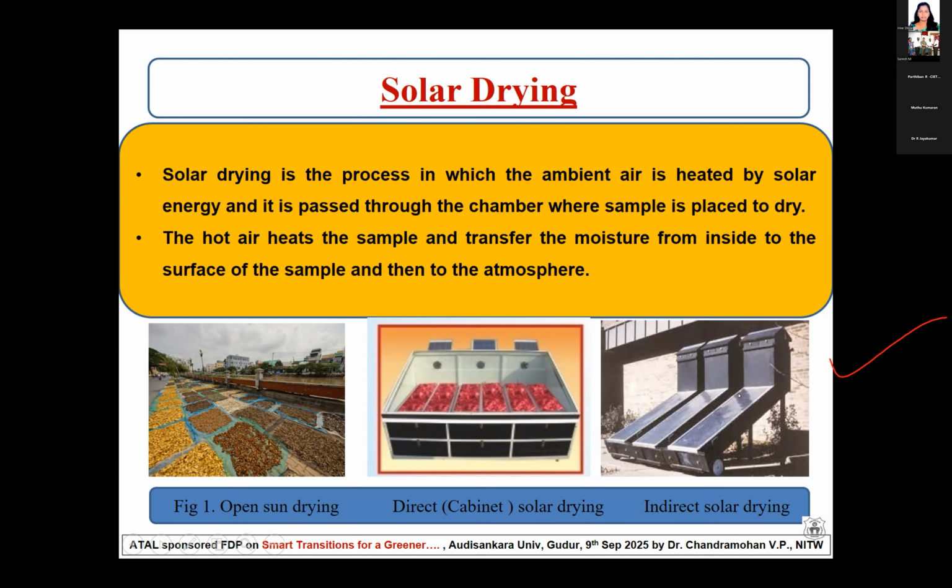And then here in the solar air collector, there is an inlet. The air will be collected inside and then passed through the solar air collector. It is a simple rectangular tunnel only. The air will enter inside and be heated because of the glass plate. Now let us assume the fresh air temperature will be around 35 degrees Celsius. After heating, the air temperature will be 70 to 80 degrees Celsius.